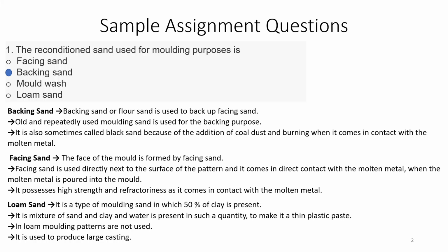Okay, so the first question was: the reconditioned sand used for molding purpose is facing sand, backing sand, mold wash or loam sand. So the answer was backing sand. In case of backing sand, it is used to back up facing sand.